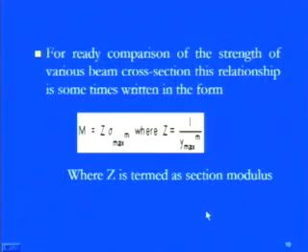And the last one is for the strength of this particular beam of any cross section, we can simply give with some relation, and that relation is coming with the section modulus Z. As we defined earlier also, the section modulus is always computing the geometrical parameters, like you see if we know the location at which the fiber is there which experiences the maximum bending stresses.